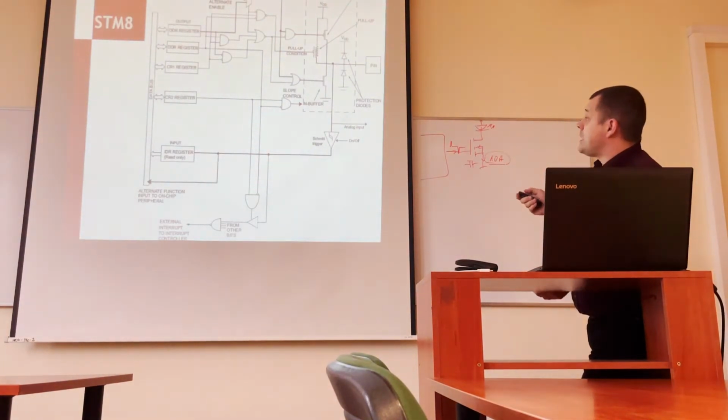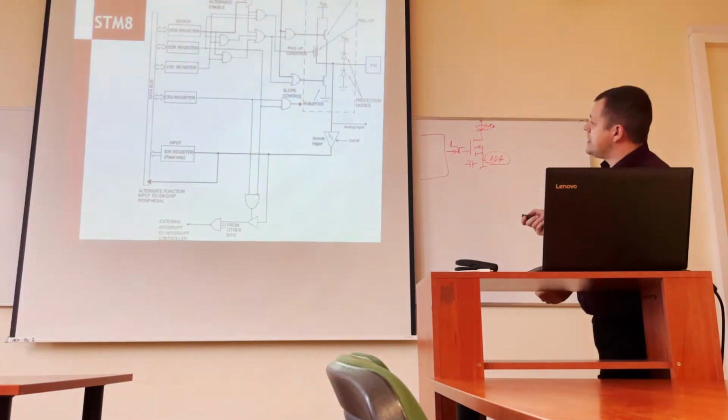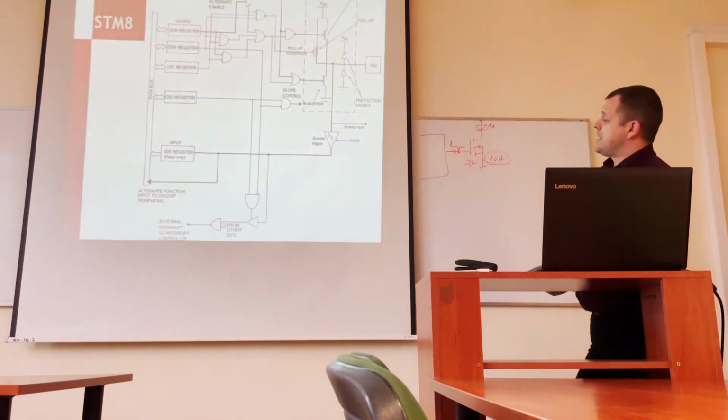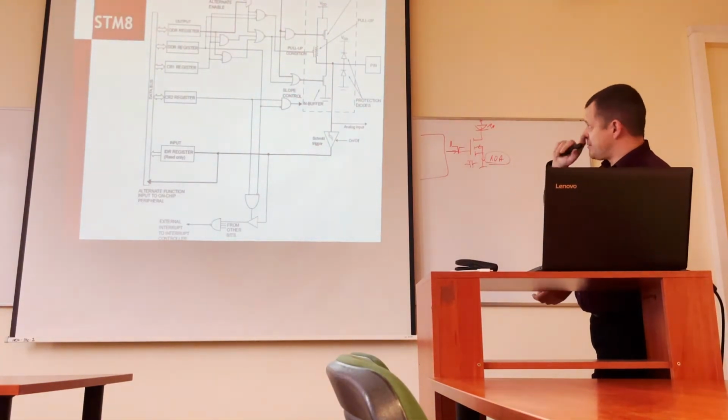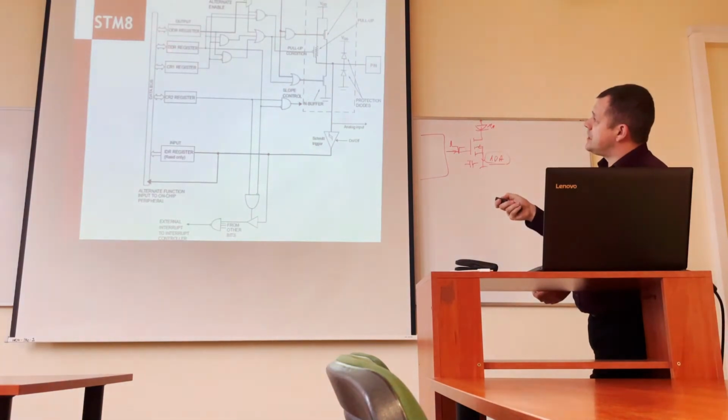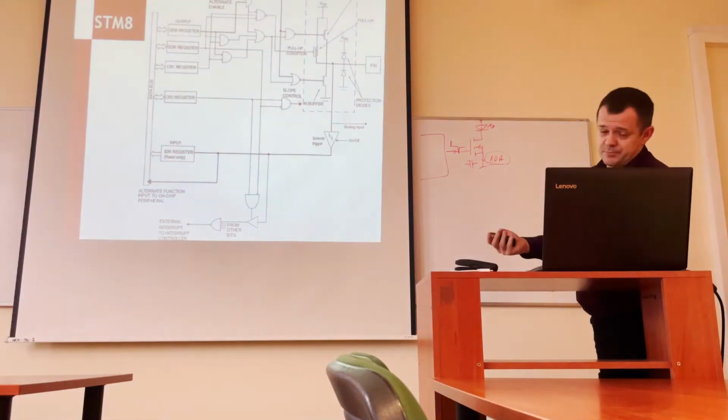Then we've got some pull-up, no pull-down here, as you can see. The Schmitt trigger with the analog input somewhere here. And there is the important stuff, the registers that are necessary for servicing the port itself. And then from this slide you can read that the register set for changing the direction is the data direction register, DDR, in this microcontroller.